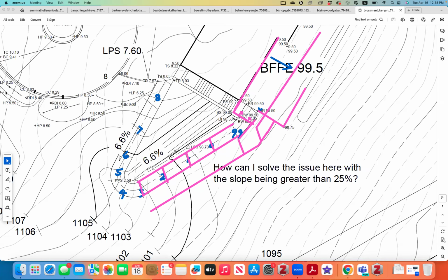Now you have more room, right? You're going to redraw this connection. Redraw this connection. Yeah, this will be the turning area. It could go down to about 2% there. So the next thing you will need to do is to make sure you correctly calculate the top of the ramp, because it's important for you to have the right location for the 8. All right. So the 8 is important. And then you offset by 50, right? By 50 to get down to the bottom ones. Okay. So that's how you should kind of revise your ramp.